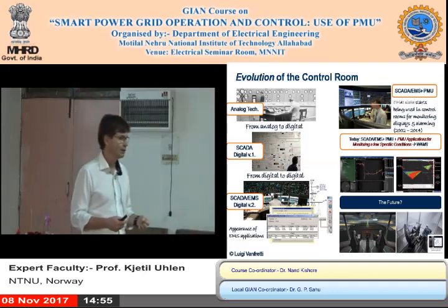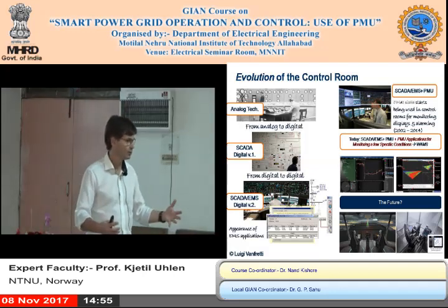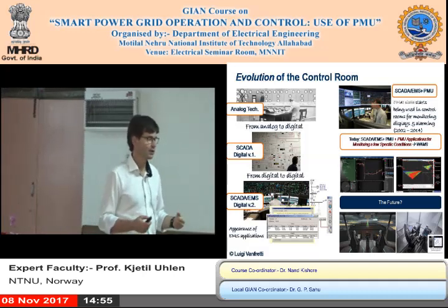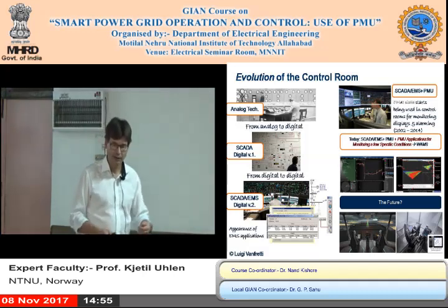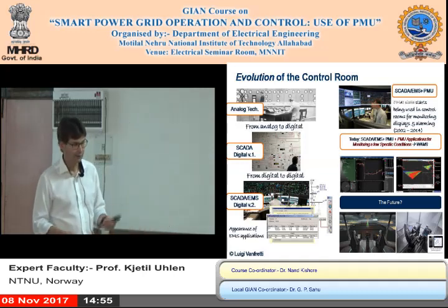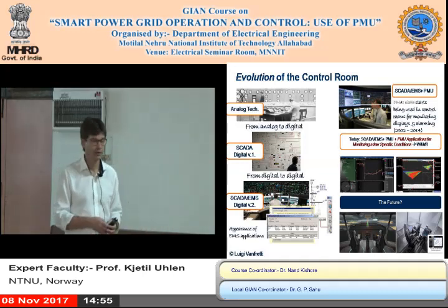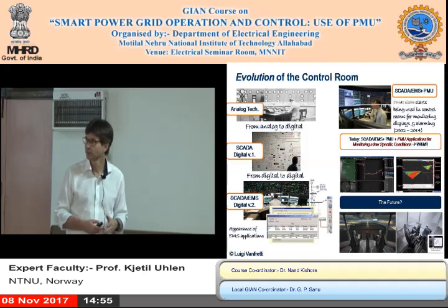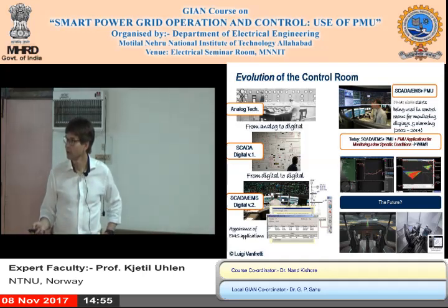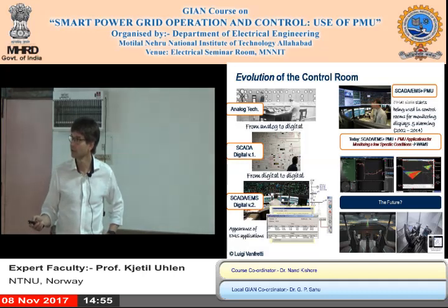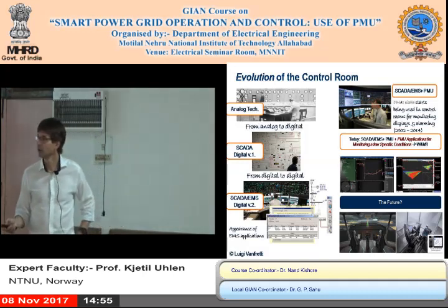You have state estimators which could provide you with a power flow solution, and you could do, for example, contingency analysis. You could check how much reactive power you needed to keep the voltage at a good level and so on. So very much this is where we are now, but we're heading into this, where we are introducing phasor measurements into the SCADA EMS system.